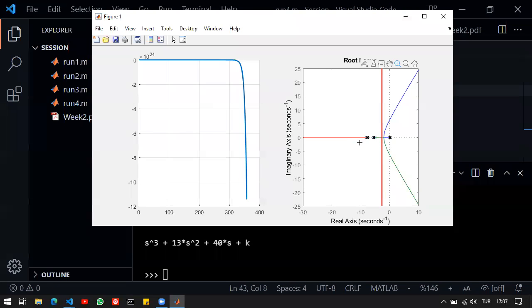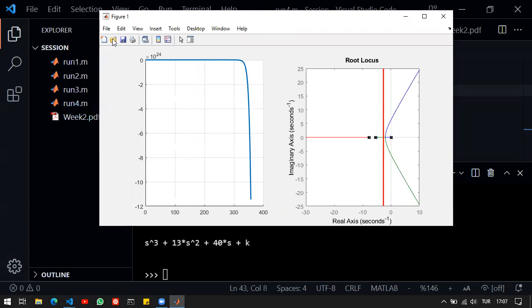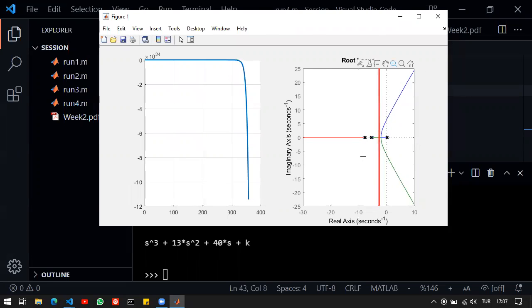So therefore, for such occasions, you have to somehow affect the root locus itself and then choose a PD-type controller. That will be basically the controllers that we address in the upcoming weeks. But for the P-type controller, there does not exist a controller that can result in a settling time of 1.5.